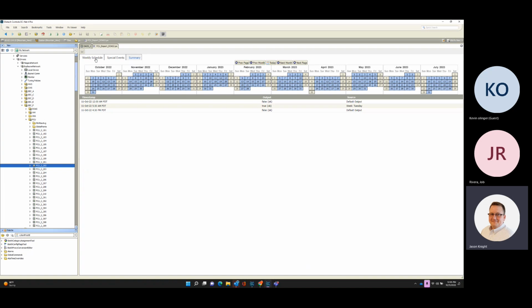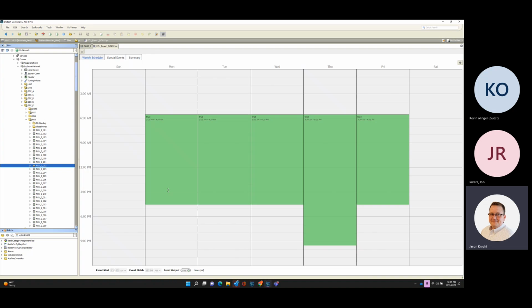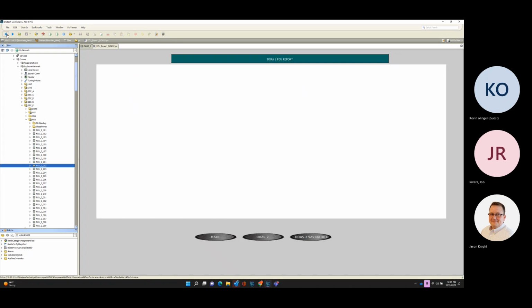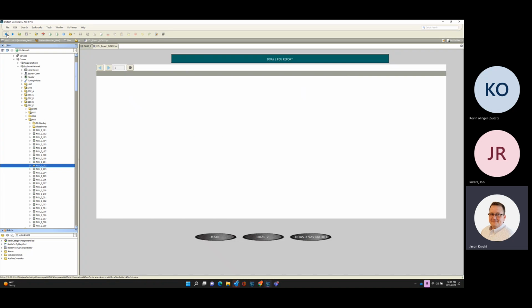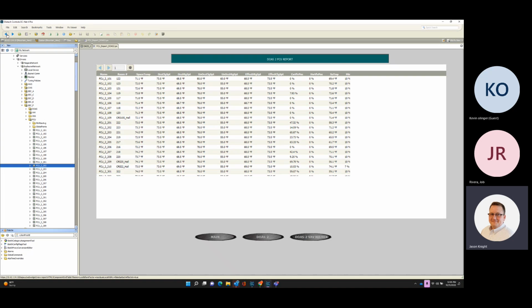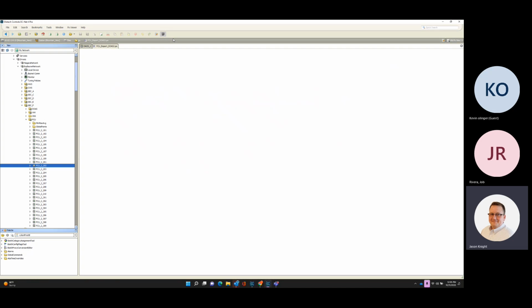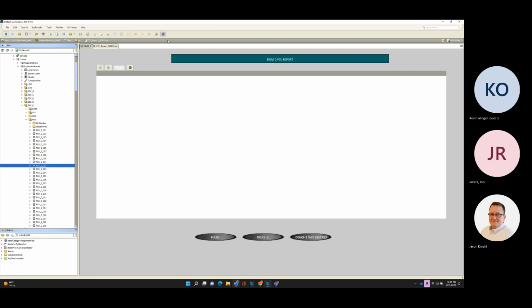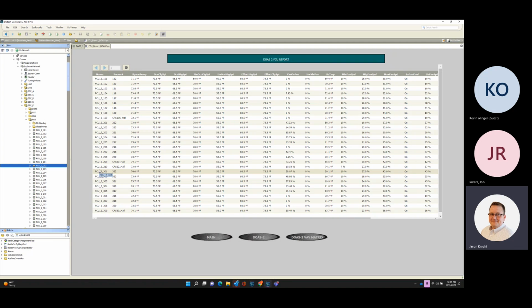That individual schedule has its own morning warm-up routine built into it. So if any one of these units starts, it kicks the DOAS on every morning. If any one of the units were put into the bypass for the occupancy override, it'll kick the DOAS unit on. Okay. When it follows the individual schedule, let's say that fan coil 2105, let's say it took an hour